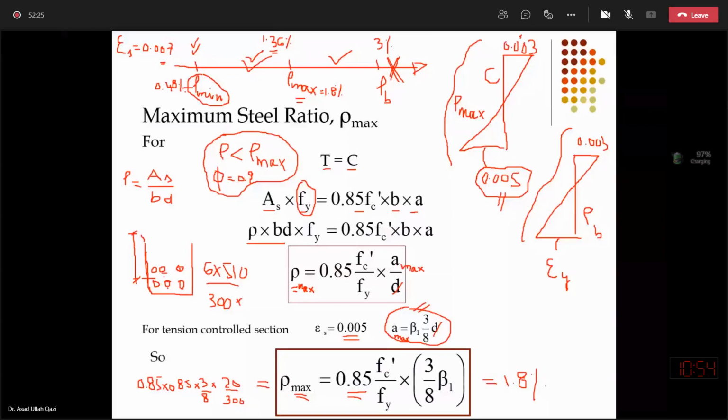Actually, just suppose out of 450, I subtract 100 millimeter as the cover, so it means I will be then left with 350 as effective depth over here. So it means now the same cross section with one more steel layer inside will have the reinforcement ratio.